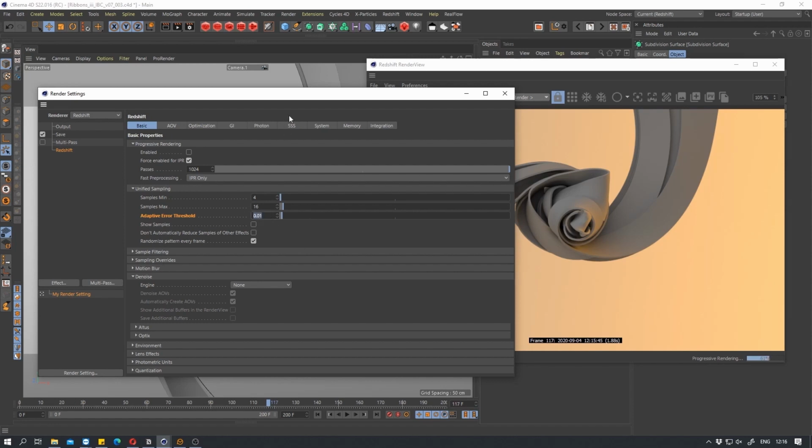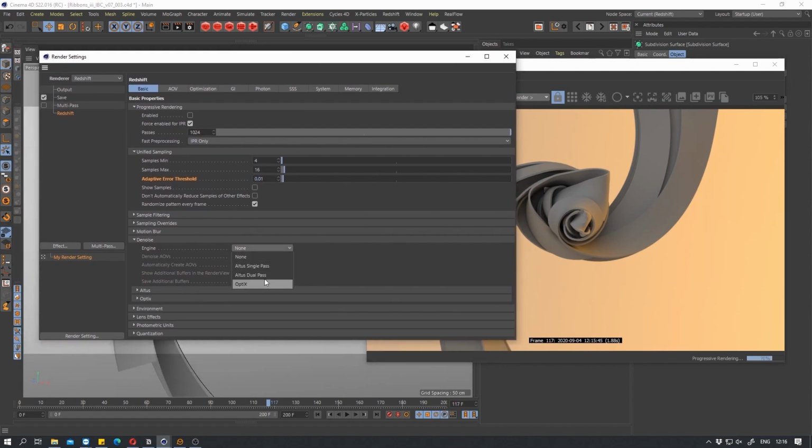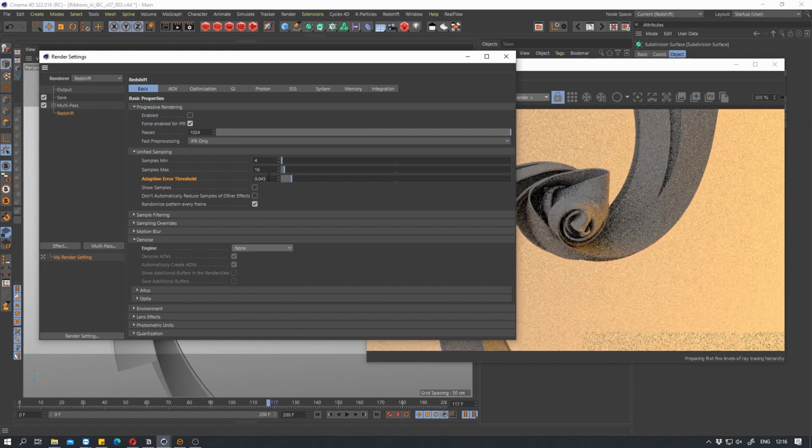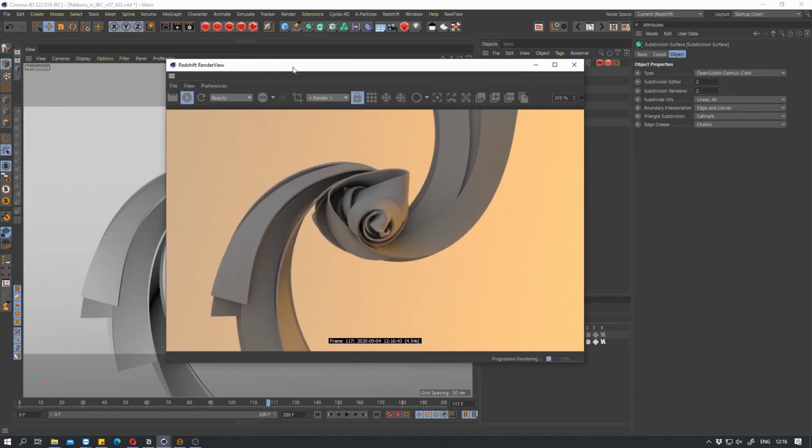One thing that I sometimes do if the render is taking too long is actually to lower the quality here, like 0.045 or something like that, and turn on OptiX, which is pretty good. Excuse me. Because I don't have a big render power in my workstation, if I have loads of reflections and refractions and all that, this actually works pretty well. Not every time, but most of the times it does. Okay, so these are my settings now. They are working for me.